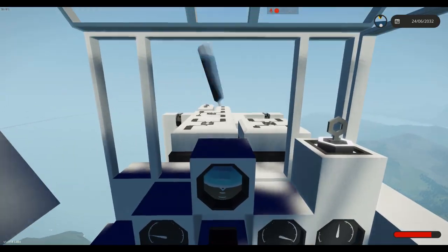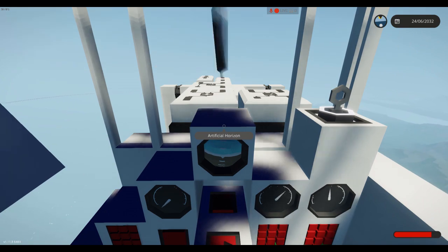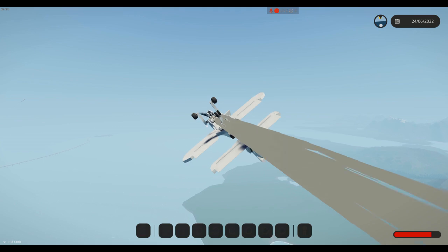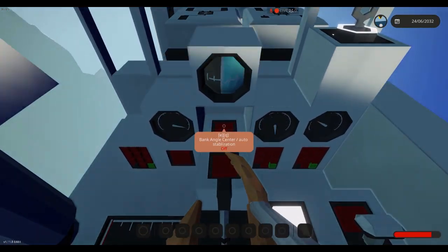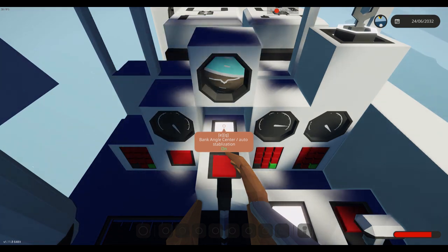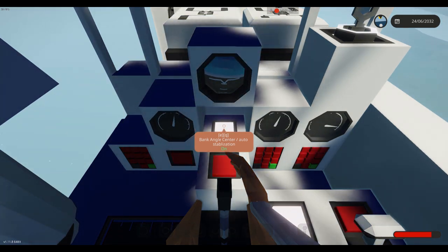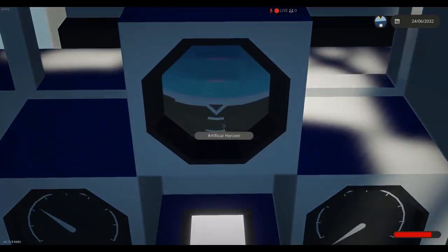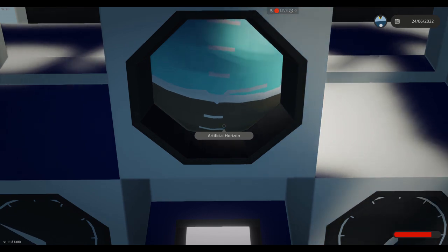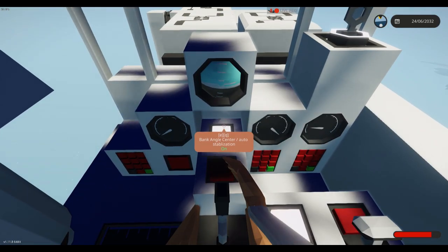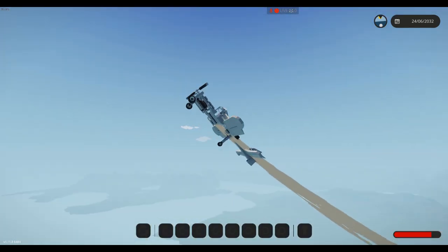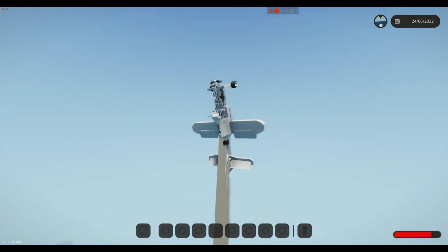And so keep that in mind. Additionally, if you're going to be doing extreme flight maneuvers such as this, such as barrel rolls, I recommend you keep your center hold system turned off, but when you return to normal level flight, you can just turn on your center hold system, and you can still make fine adjustments such as this. But again, for extreme flight maneuvers such as barrel rolls and loop-de-loops, I recommend turning off your center hold system for optimal performance.